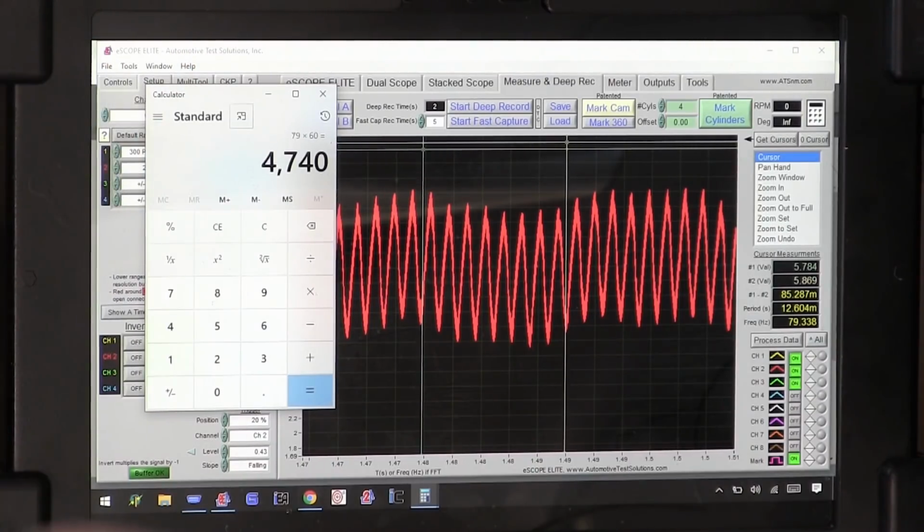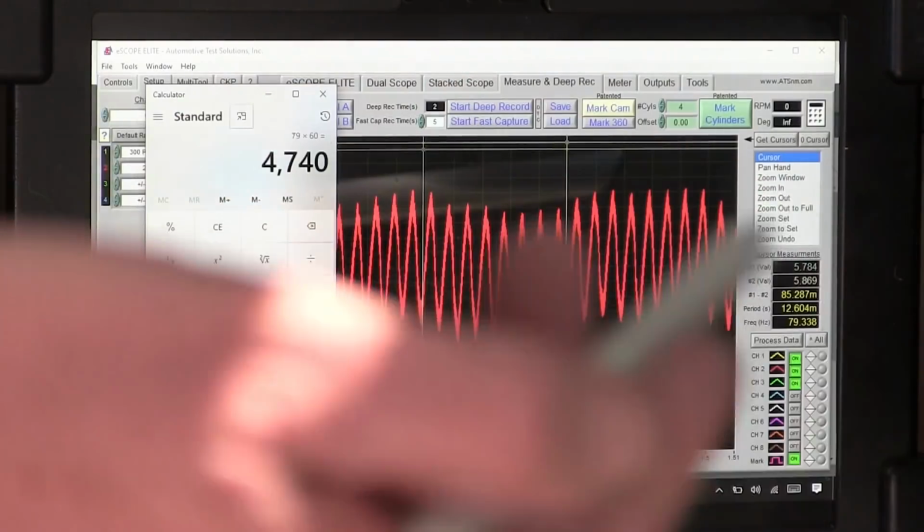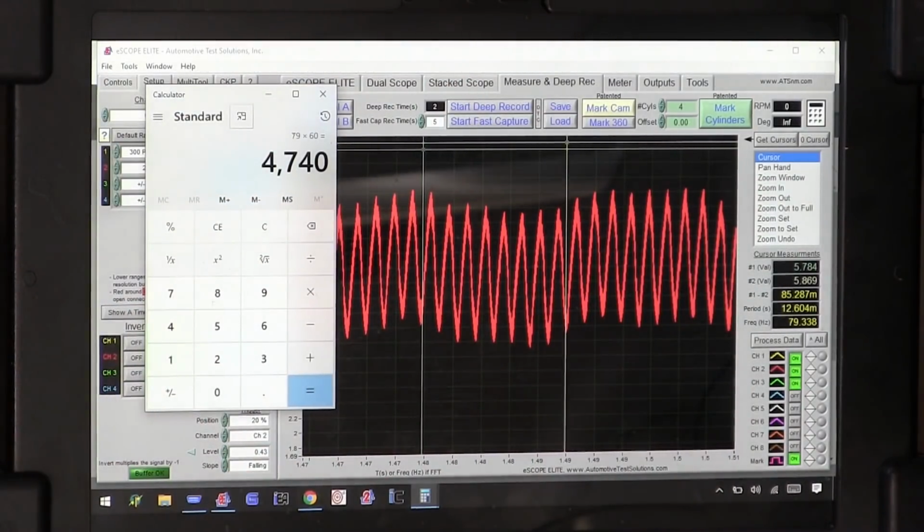If the pressure went down to 2 psi, the pump would have to go faster. In this case, the line is plugged. So somewhere from the tank to the engine, that line has a restriction in it. The aeration is just as it's going by the restriction, it's cavitating because the line is partially restricted or kinked or whatever's wrong with it. But you could put as many pumps in this car as you want and you're not going to fix this problem. That's why I'm here at the shop, because I put a pump in and it didn't fix it.